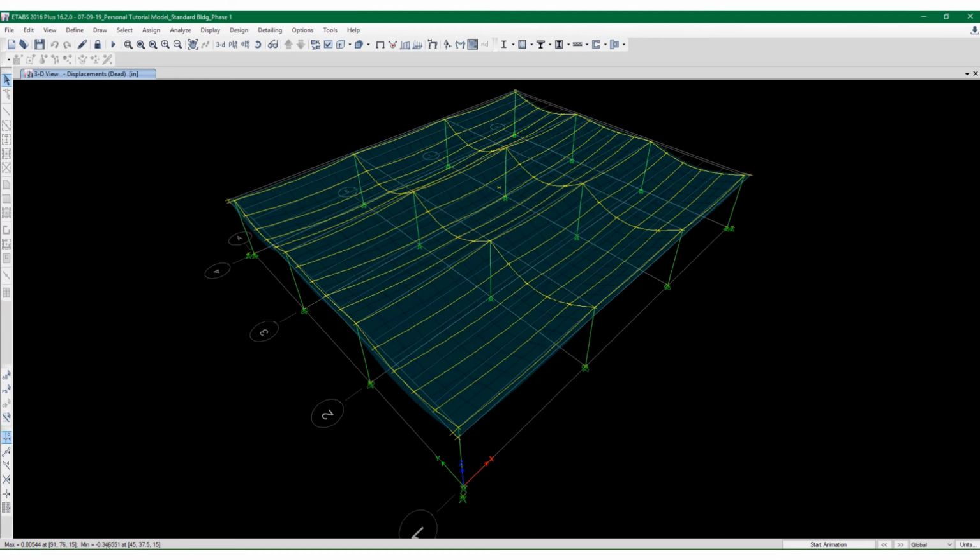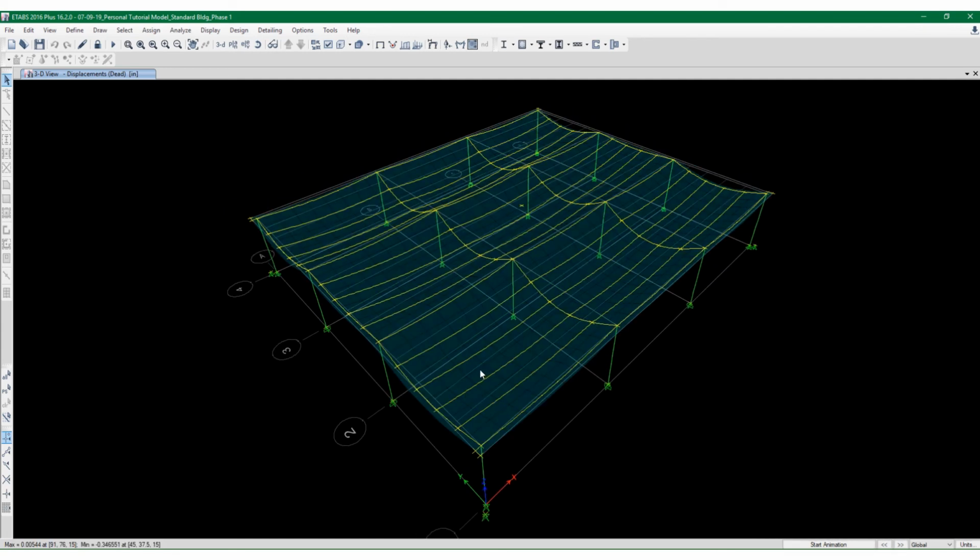Again, with the rigid diaphragm property that's set here, which is actually incorrect for metal decks, or typically would be incorrect. You would have to go through a certain analysis to determine if your diaphragm is rigid, but most likely the diaphragm for metal decks is almost always treated as not rigid, unless ASCE tells you to treat it as a rigid diaphragm by some type of analysis. Either way, this diaphragm would be a semi-rigid diaphragm, right? It's the only other option.